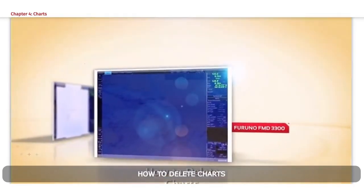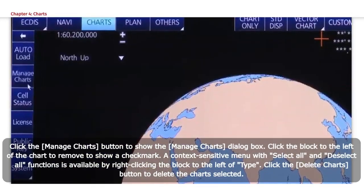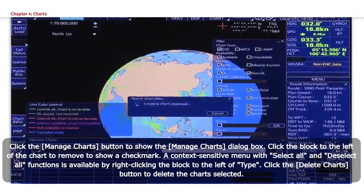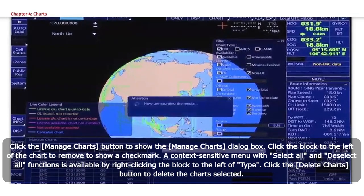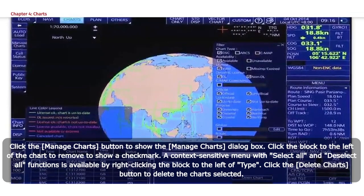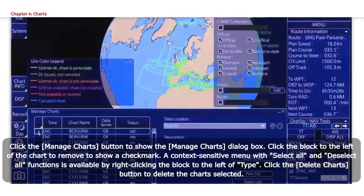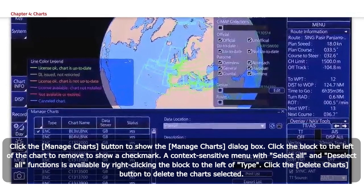How to delete charts. Click the Manage Charts button to show the Manage Charts dialog box. Click the block to the left of the chart to remove to show a checkmark. A context-sensitive menu with Select All and Deselect All functions is available by right-clicking the block to the left of Type. Click the Delete Charts button to delete the charts selected.